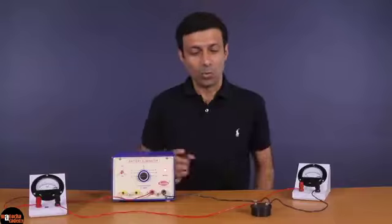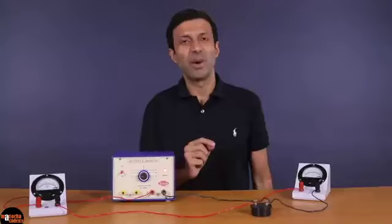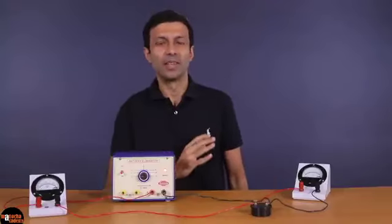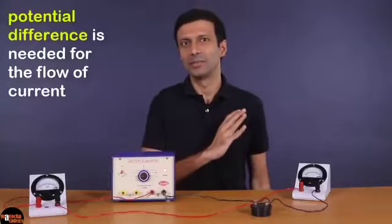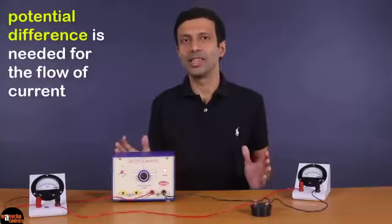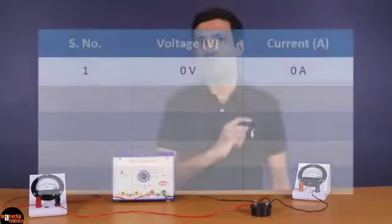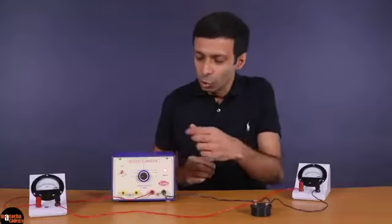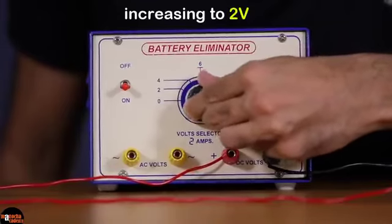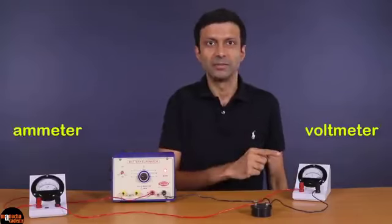As expected, when the potential difference across the wire is 0, the current in the wire will also be 0, since potential difference is needed for the flow of electric current. So if there's no potential difference, there will be no current. And this is our first data point, 0 volts and 0 ampere. Now let's increase the voltage to 2 volts and check the reading in the ammeter and voltmeter.